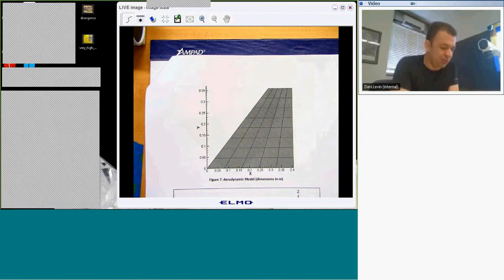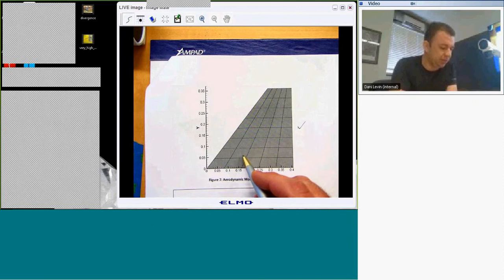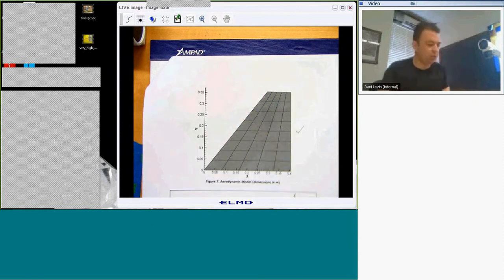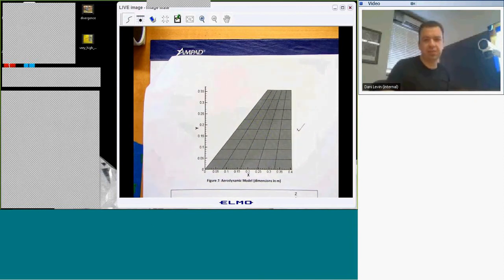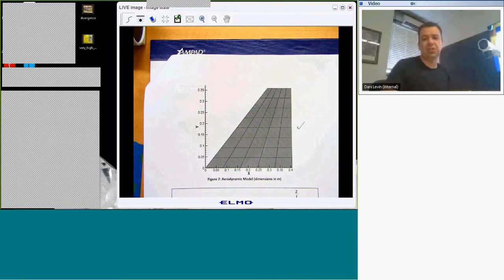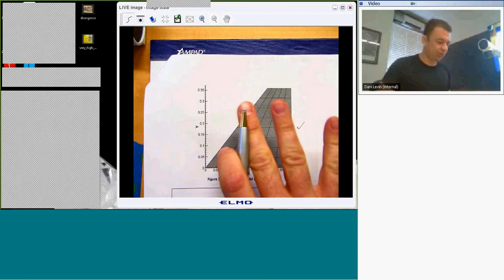So this is our aerodynamic model, crafted with aero boxes, and each box will generate the unsteady lift and moment. It's more generalized. It will actually generate 6 degrees of freedom, 3 forces and 3 moments, but some of them might be 0 because they aren't really active, for example, in-plane motion for aerodynamics.